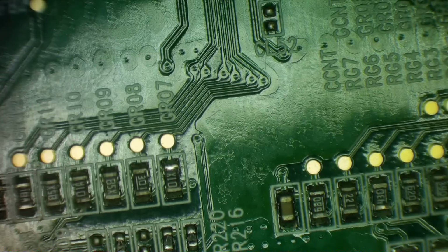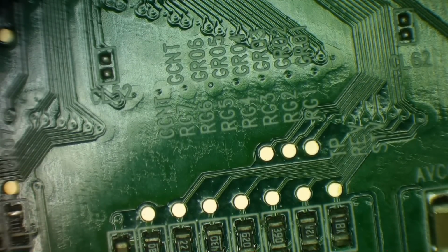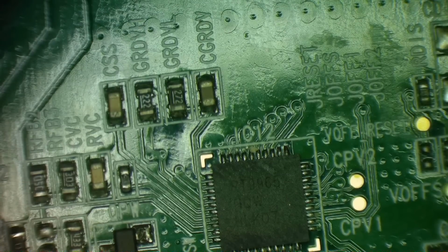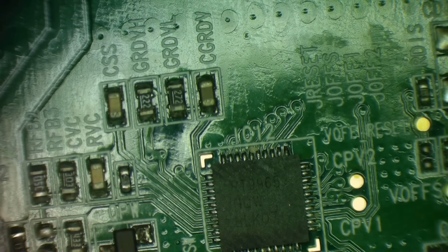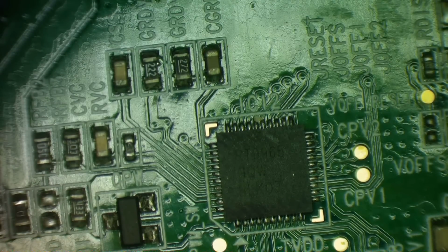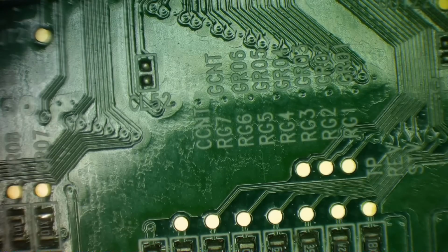And in fact, they say like RG. These are gamma voltages. So we can look up this chip, but the fact I've got a load of ascending or descending voltages here suggests to me that the gamma chip is working. If not, then you usually get a picture, but the contrast is all wrong, or the brightness is all wrong. But we can have a look. But I think that's working just by the voltage I was seeing in this area.